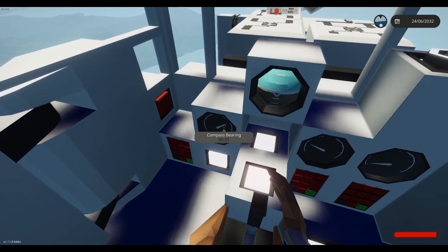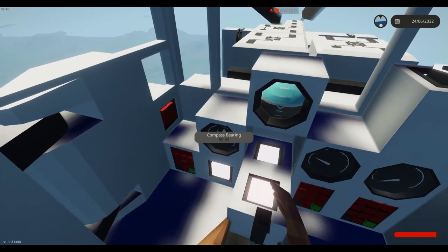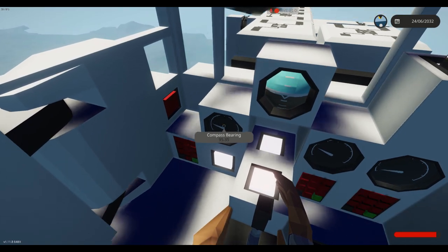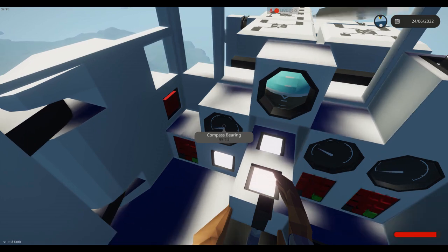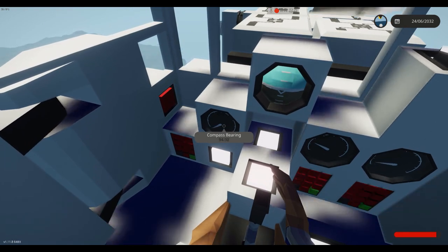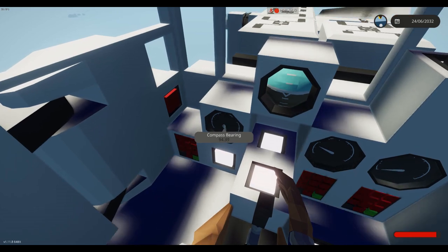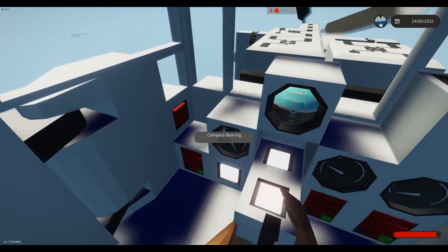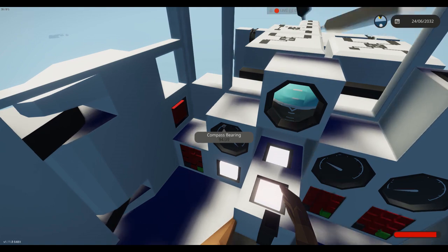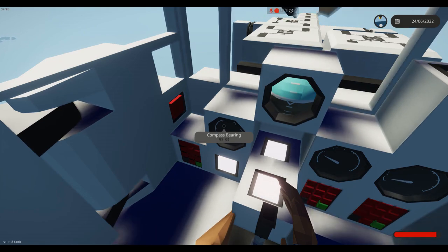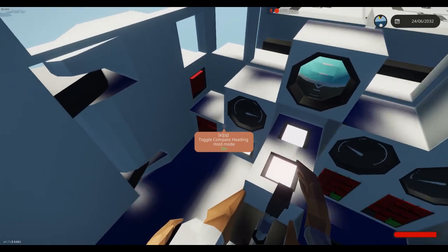So that way, if you plug in 359 into your compass heading hold, it will get to 359 and it will not ever exceed a value of 360, or rather 0, and then do the full loop to go around. It'll go from 0 all the way to positive 1, 2, 3, all the way to 360. You do not ever want that to happen. And so you just need to tune your PID to be very sensitive and very gentle. Currently, this system is still in a questionable state since we have not reached 90 yet, and I input 90.